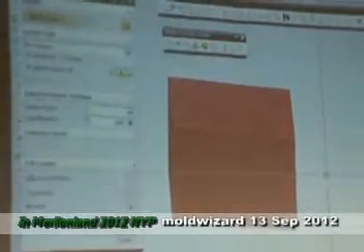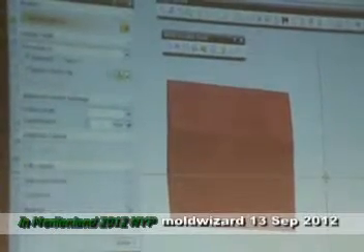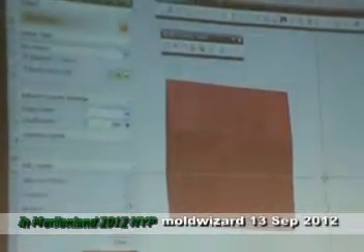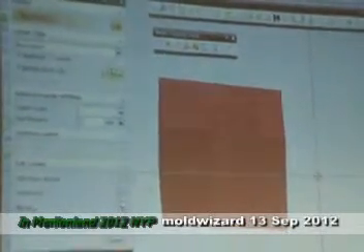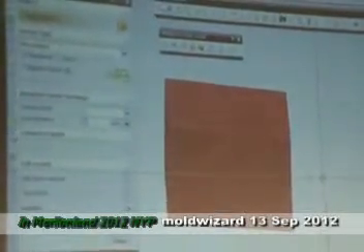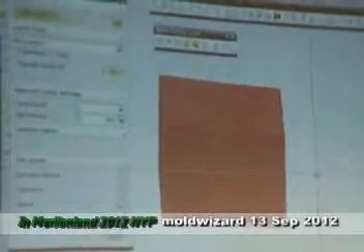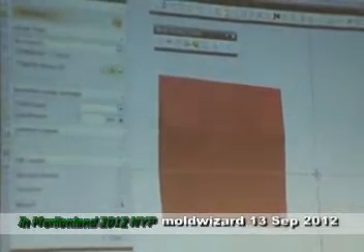This is the product profile, whereas by doing the mold cutting, this will be the cutting line level, and this will be the insert, and this will be another cutting line level, and this will be the other insert, and these are the cutting lines.